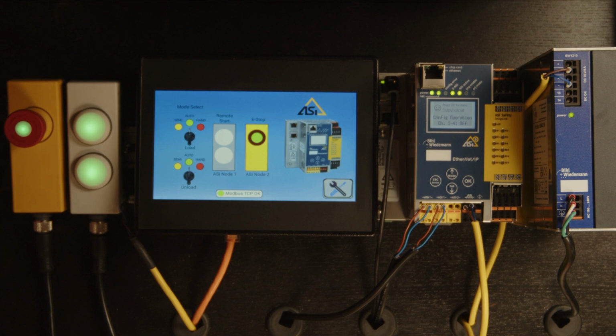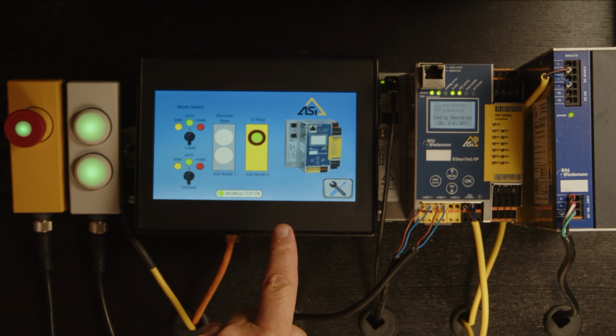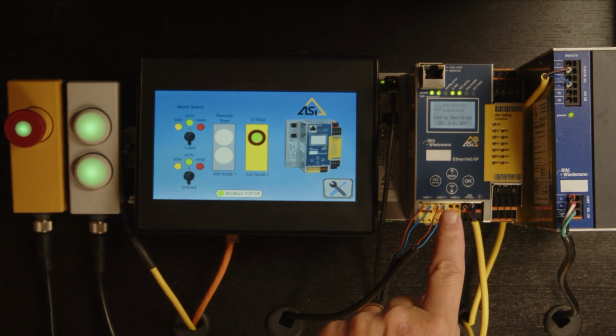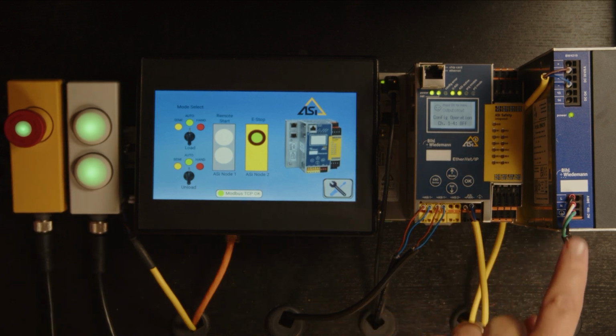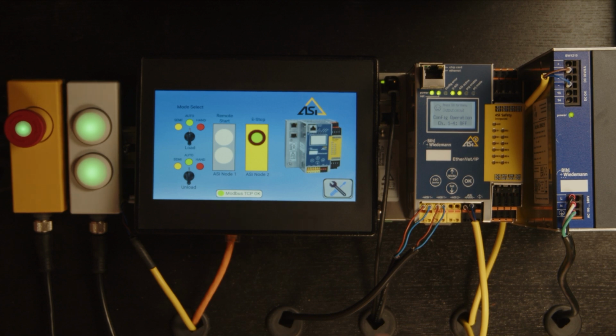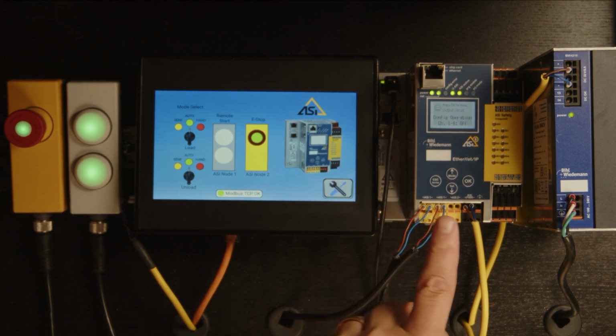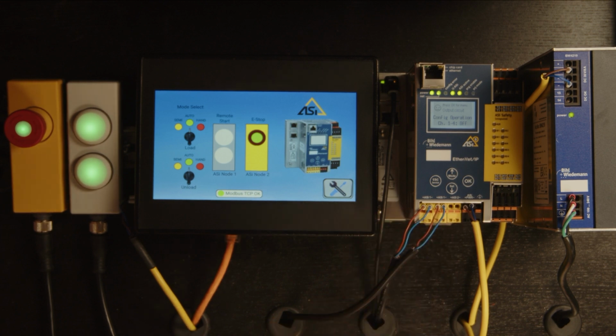Now, through the wonders of pre-recorded video, you can see I've now added my Horner OCS all-in-one controller to our ASi demonstration here. Between our ASi slave devices, which we just configured, and our ASi gateway, we've also, of course, got our ASi power supply. As we just mentioned, the ASi gateway is controlling the slaves directly at a high rate of speed, probably an update rate of about 5 milliseconds or so. And then all of the ASi input and output data are being exchanged over Modbus TCP, also at a pretty good rate of speed, about every 10 milliseconds or so.